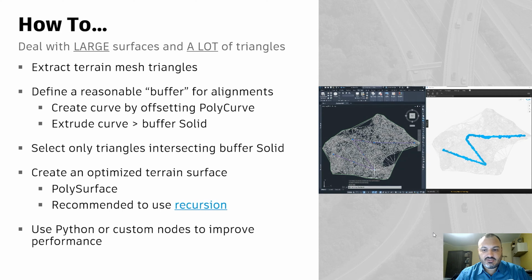And this is critical for the generative design study because you can even have failures if you don't do that. Like Dynamo can run out of memory, or it's going to take very, very long before you can actually complete a single cycle. And this is important because the generative design study happens with multiple processes in parallel that are trying to solve the same problem with different inputs.